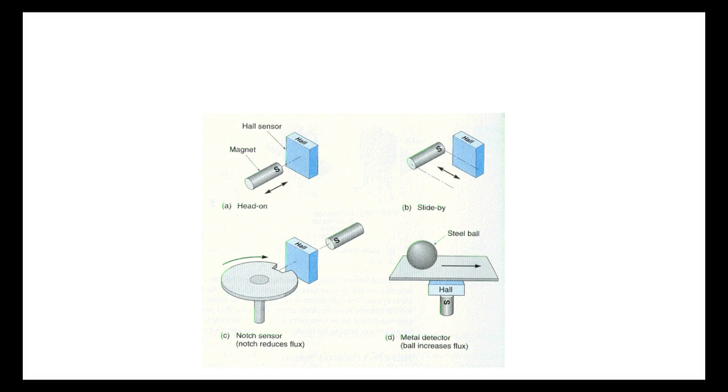Well, this is solid. We're not talking about that thing you're holding in your hand anymore. This is an electronic sensor. This is solid state. It's sensing the magnetic field electronically. So we don't have contacts inside these guys. We got some type of electronic device that either simulates an open contact or simulates a closed contact. But these guys only sense magnetic fields. But what's nice about this, that reed switch has got to have a magnetic field of a certain strength before it does what? Before it senses it. These guys right here are pretty good. These are pretty good magnets.